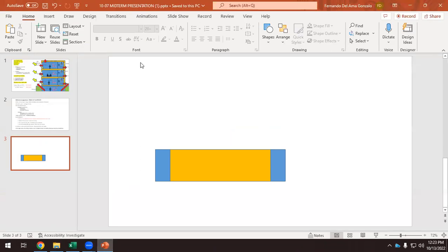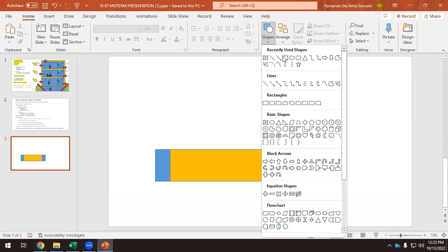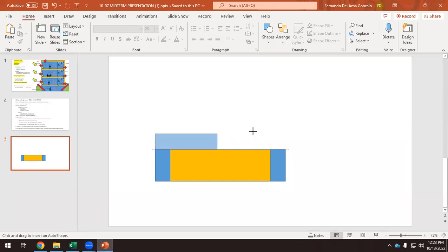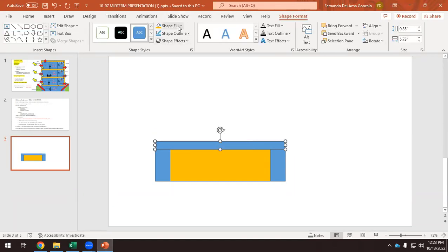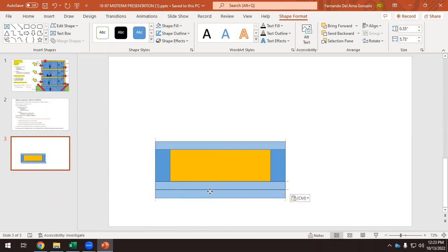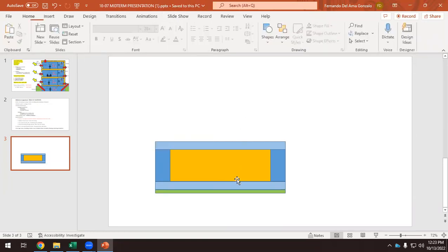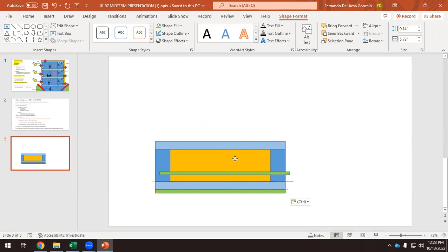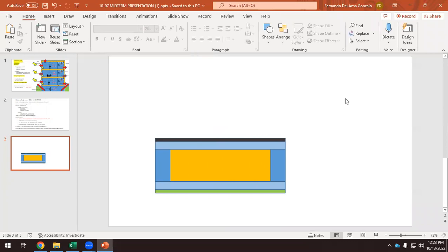So if we have this, we have another air cavity here with a different color. Another air cavity underneath this, and there was a gypsum board or a gypsum false ceiling here. And then we have the asphalt with a different color. Okay, so that was the roof, and you had to calculate the thermal transmittance through the rafters, through the thermal insulation, and then the U average.